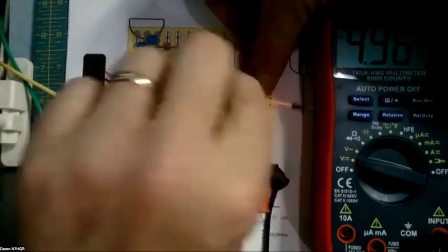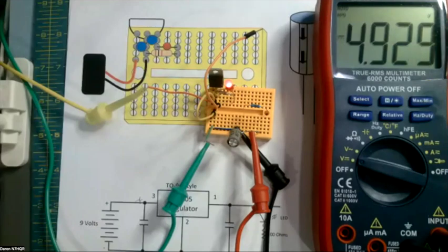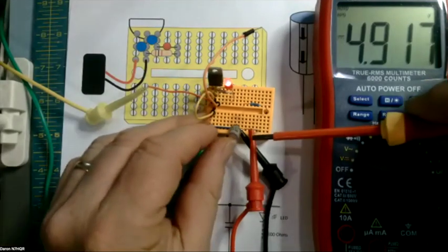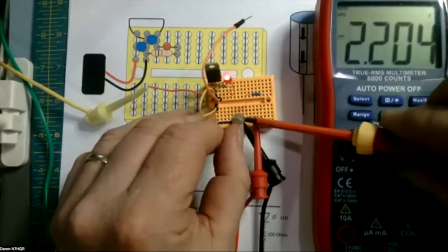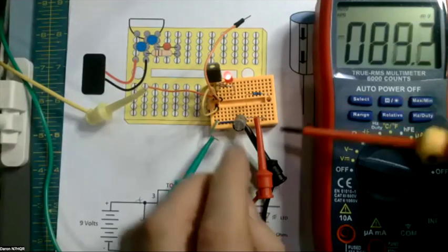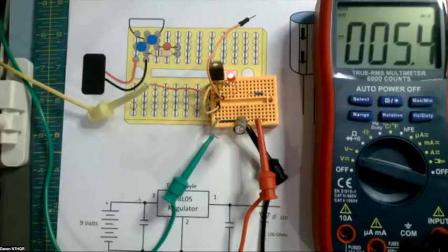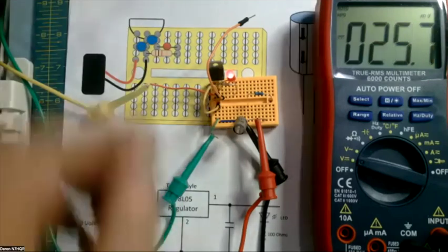All right. Okay, there goes our 5 volts. Now we're gonna go back down. Yeah, it's discharging through the meter, and you can see it's going very slow. If you grounded it, you shorted it. Yeah, I shorted it on purpose. That definitely will discharge the capacitor.